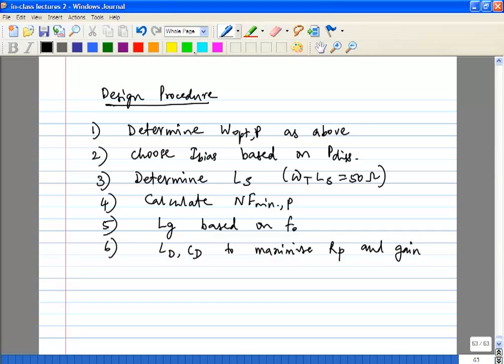So the simulator gives you the noise figure. It will give you the minimum noise figure for that condition. So you can find out how close you are, whether you're optimized or not, and so on. We'll put up a tutorial on Monday, and you should be able to get going. Now the other thing we didn't talk about at all was IIP3.